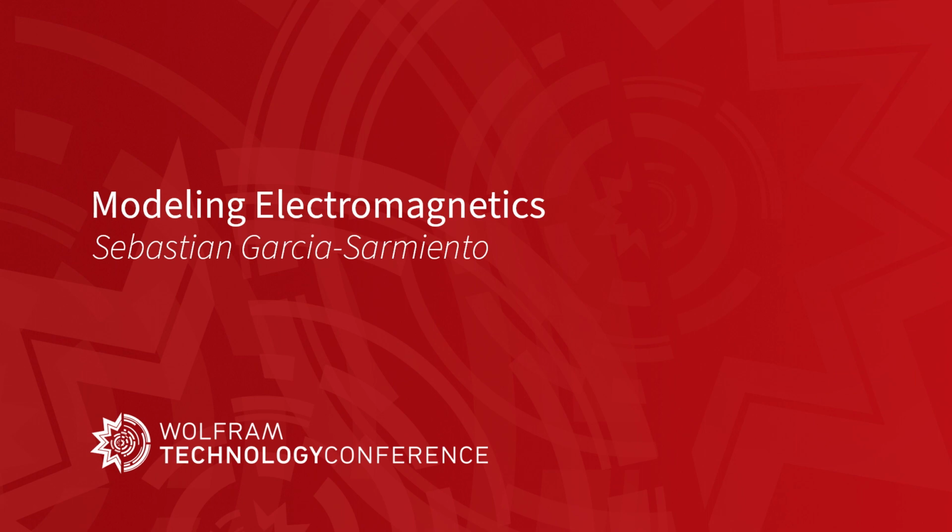Other questions: how is electrostatic turbulence handled? I don't know what you mean by electrostatic turbulence. Right now, the electrostatic equation can simulate different things, also non-linearities, and maybe with more work, you can simulate ferroelectrics. For 2D cases and axisymmetric cases, it is really easy. In the electrostatic equation, you only need to specify a parameter, the region symmetry, and that is already in the monograph: how to simulate axisymmetric models in 2D cases. We already have a model that shows how to do it. It is a spherical capacitor.